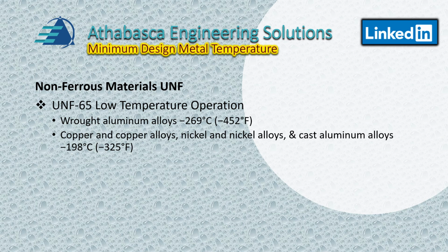Again, copper alloys, nickel alloys like Hastelloy, alloy 20, and all these things. Cast aluminum alloys, they're saying it's down to minus 198. Again, these are fairly commonly used for cryogenics. And then titanium, which I don't have any experience with personally, except for your golf club type stuff, with sports equipment. So titanium or zirconium and their alloys are down to minus 59. And that's basically it in a nutshell for Section 8 Division 1.